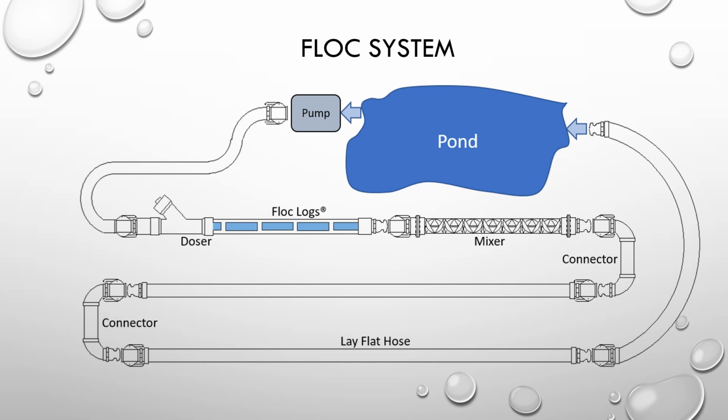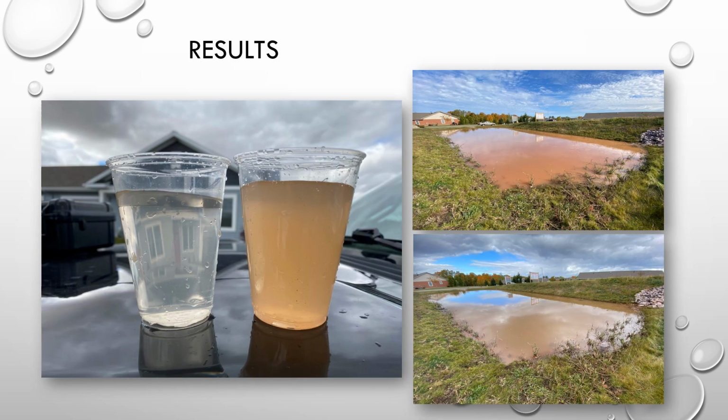Pumps and pipes really want laminar flow, but what we like is turbulent flow to create the flock. So we'll add static mixers, we'll change hose or pipe diameter, really anything to get some extra mixing going on in that hose. And then, of course, we want to make sure we have enough hose length and enough mixers to get that flock fully formed before it discharges. And again, if we do all those things, it's a different system, but it's the same material, it's the same principles, and we're still aiming for around 20 to 30 NTUs and that 90 to 95+% turbidity removal.